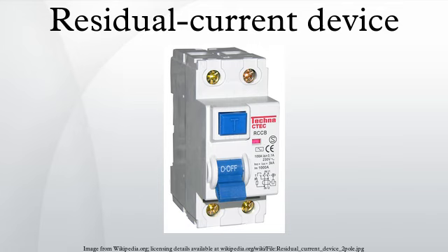Type: Standard IEC 60755 defines three types of RCD depending on the characteristics of the fault current. Type AC, RCD for which tripping is ensured for residual sinusoidal alternating currents. Type A, RCD for which tripping is ensured, as for type AC, for residual pulsating direct currents, for residual pulsating direct currents superimposed by a smooth direct current of 6 mA, with or without phase angle control, independent of the polarity.